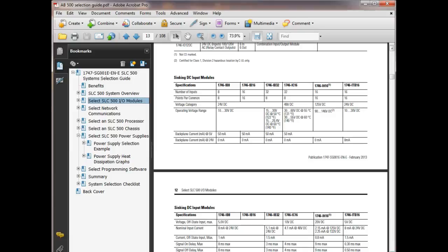With Allen Bradley PLCs though, the addresses you get are assigned by where these things are at, right? You understand? So when you get a modular PLC, the addresses they get are assigned by which slot you put that thing in.